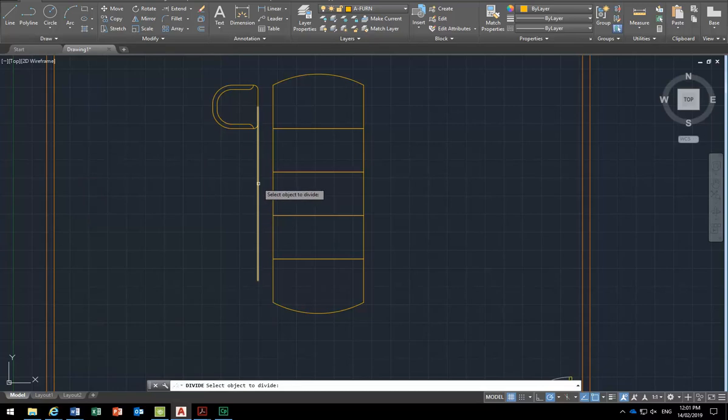I'm going to select my line and then type in, now what can I think it's going to be, oh, they're doing 8. Okay, I see why, because they want to have, yeah, so we're not going to use every point. All right, so they want 8 segments, so it's going to have 8, enter. You'll see why when it's done, it will make more sense once you see all the points. So it has divided the line, even though it's all still one line, it's put some points there to divide it up. But we can't see the points.